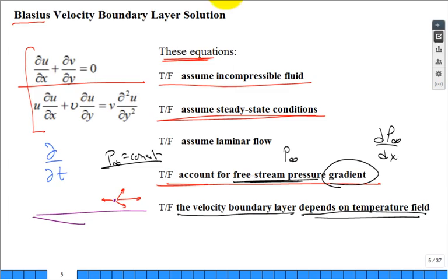In this equation right here is mu over rho. Isn't that our kinematic viscosity? And you're saying, but everybody tells me, and my experience tells me, that the viscosity is a function of temperature. But when we solve it, we're not solving for nu varying. We're solving for a single value of nu, meaning a single value of viscosity, meaning no temperature effect. That would be the most likely effect of temperature feeding into this equation. But no, we're not going to do that. So there you go. Let's press forward.